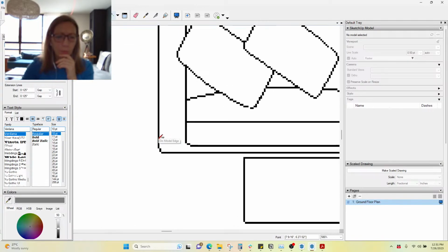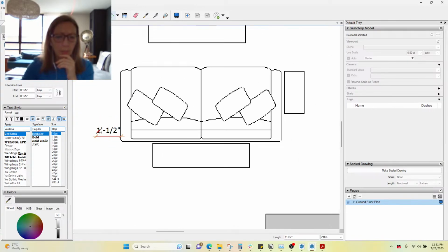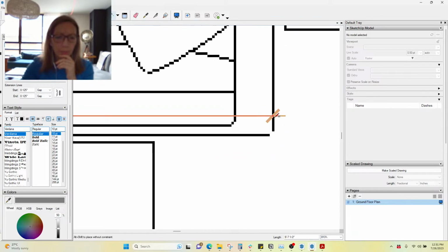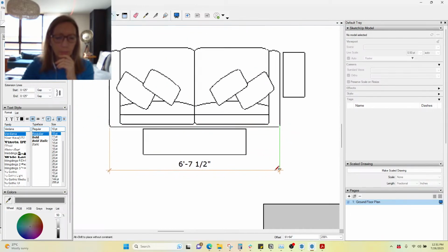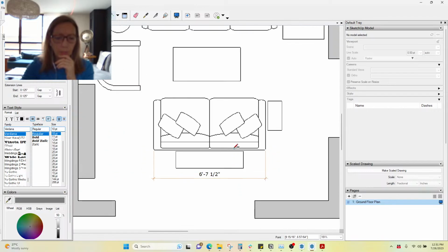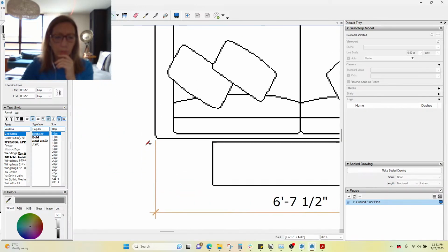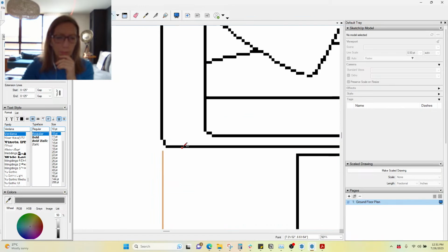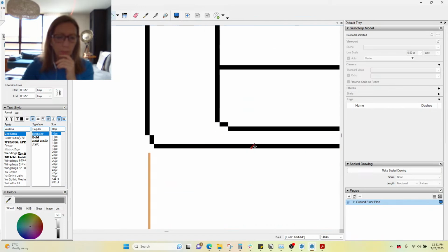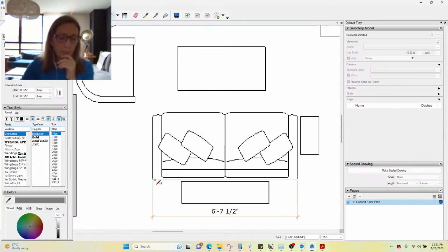I find that when you're dimensioning in layout, you got to get real close and personal on the lines themselves, and people are often looking for that green little thing, but I'll just go along and find the red one if the green one isn't popping up. The red one does mean that you're at the edge of the object in the model, so if the green one's not there, then I use the red one.